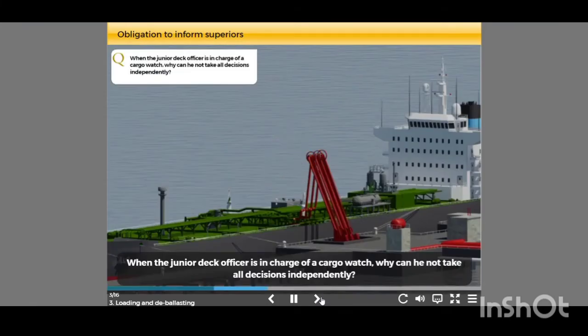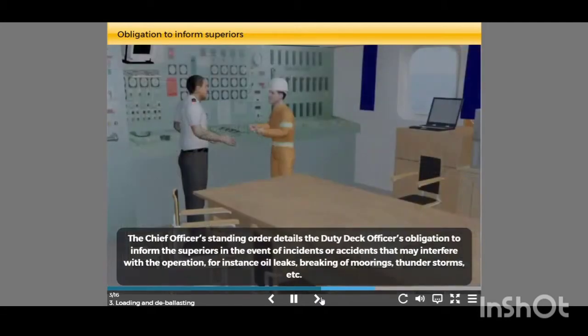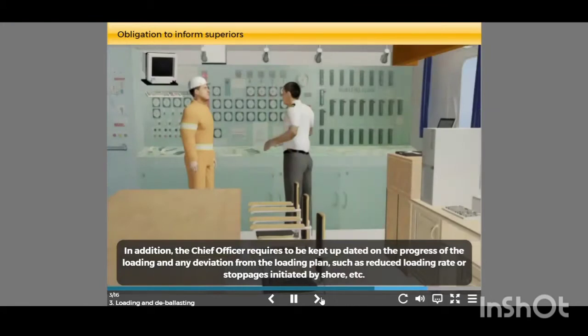When the junior deck officer is in charge of a cargo watch, why can he not take all decisions independently? When the loading is well underway, the chief officer delegates the practical operation to the duty deck officer, pumpman and boatswain. The chief officer's standing order details the duty deck officer's obligation to inform the superiors in the event of incidents or accidents that may interfere with the operation, for instance, oil leaks, breaking of moorings, thunderstorms, etc. In addition, the chief officer requires to be kept updated on the progress of the loading and any deviation from the loading plan, such as reduced loading rate or stoppages initiated by shore, etc.